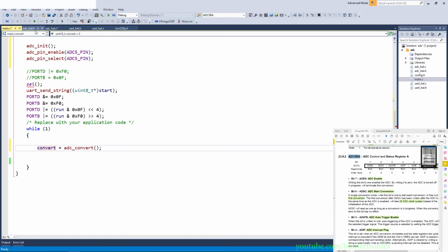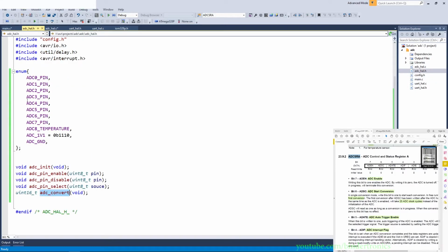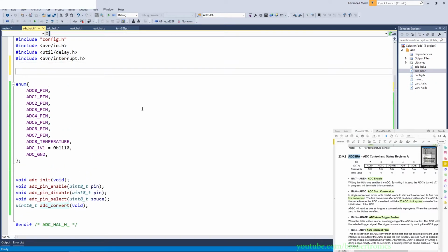Then I'm going to add something else to the header file, which is a conversion macro. Under our includes, we're going to do #define ADC_VOLT, and that is going to take a parameter of x. We take x multiplied by internal 5.0 divided by 1024.0. The .0 just makes sure the compiler knows it's a floating point number that we're converting. This is just a macro so that we can convert to voltage.